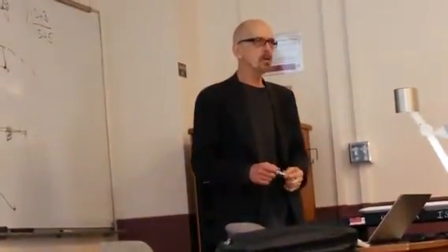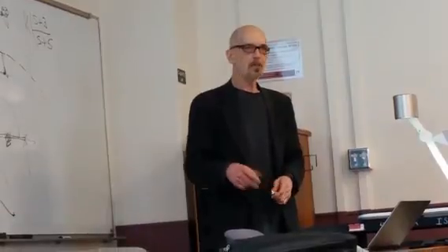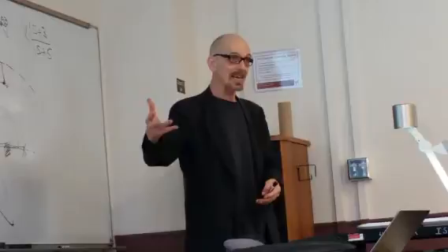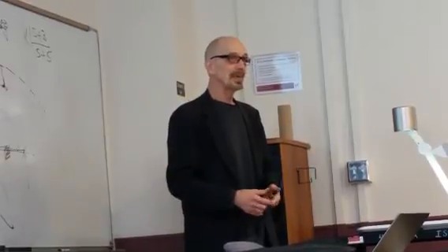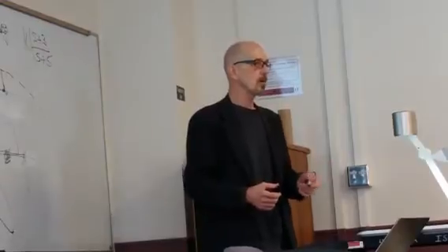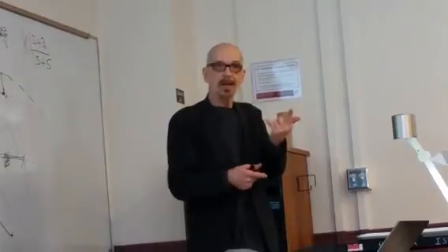Why do I want unity static gain? So you don't mess with the other stuff. So I don't mess with that 1/30th, which was what I needed for my steady state error to be what it should be. Right? Because you're letting S go to 0 for steady state error. So if the additional compensator you include has unity static gain, when S goes to 0, it's 1, and it hasn't messed with your other specification. And again, this is another biggie. This is a 15-pointer.